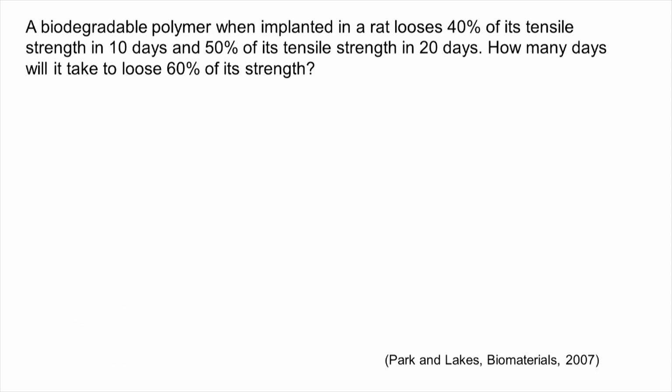So, a lot of examples of blends being used, mixing two polymers together, so we can achieve properties which are not available with one single polymer, and sometimes we may have to add compatibilizers, that means a third polymer which improves their mixing, or we can do cross linking and so on. Then we also looked at composites where we are adding an inorganic material, okay, like your glass or carbon fiber or particles into a polymer. So, it gives a lot of strength and better elastic modulus, okay.